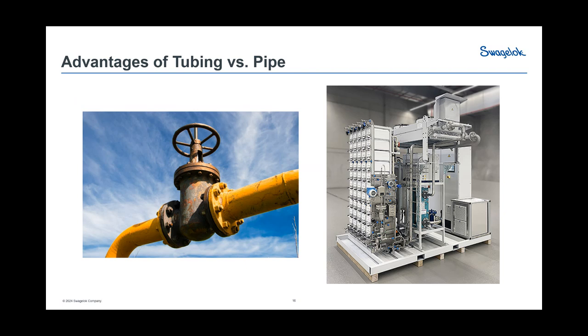Tube fittings versus flanges. You will see a couple of flanges in there, and those are basically on exhaust lines from the discharge and the cooling system. But the actual hydrogen portion of it is all held within tubing. And you'll notice valves are small, sensors are small. It makes things easier when you're dealing with small molecule gas.